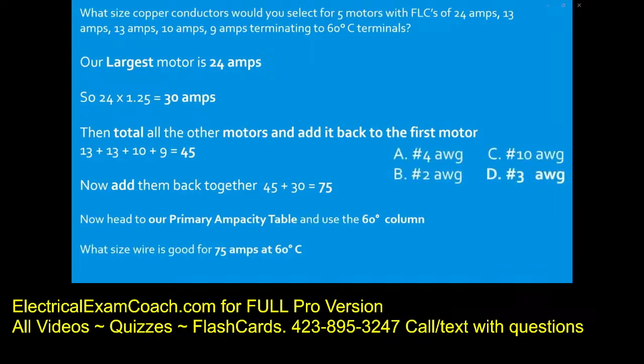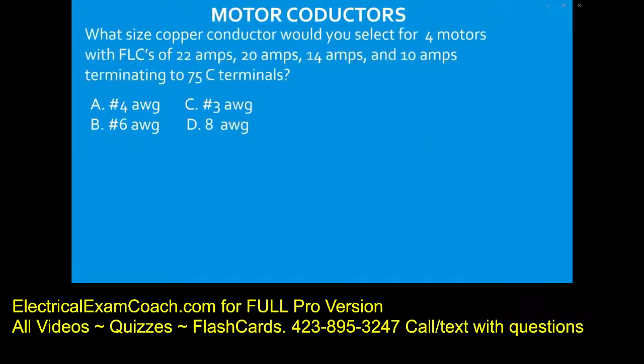Great job. What size copper conductors would you select for 4 motors with FLCs of 22 amps, 20 amps, 14 amps, and 10 amps terminating to 75° C terminals? So the first thing we're going to do is take our largest motor and do the 125%.